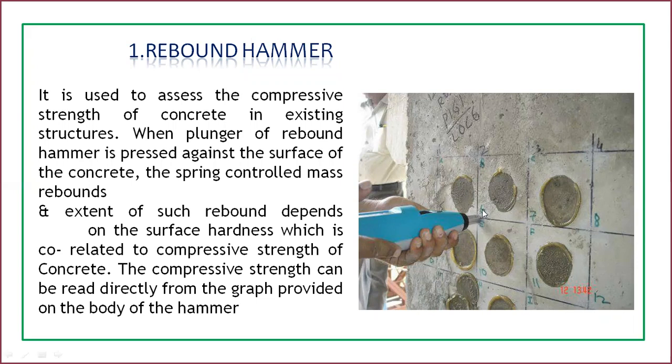See here, rebound is the concept that directly relates to Newton's third law. So the strength that we apply in the form of work in one direction is rebounding, that is, regained back with equal and opposite forces. In such a way, the similar compressive strength will be obtained as a reading directly, which the concrete provides back to the hammer.